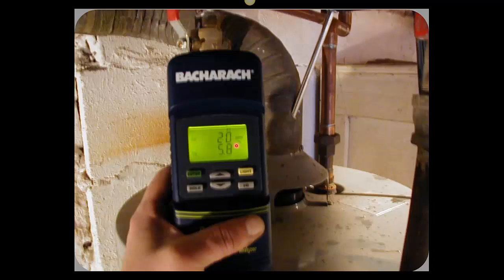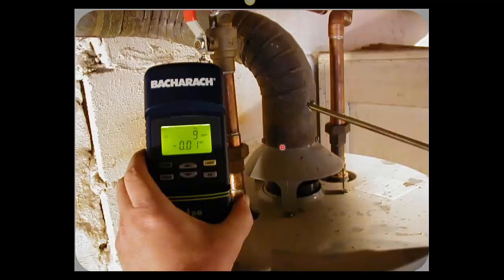Okay, but one thing I want you to notice is this, and I'm sorry this picture's a little blurry. The CO in the undiluted flue sample is 20 parts per million. Now let's go to the diluted. Now we put our probe in the wrong place. We can see we're above the draft hood. Now we've got all this dilution air entering the process. And look what my CO did. The reading has dropped by over 50%. Okay, so we're getting a skewed reading. What is really going on with that burner is down here.